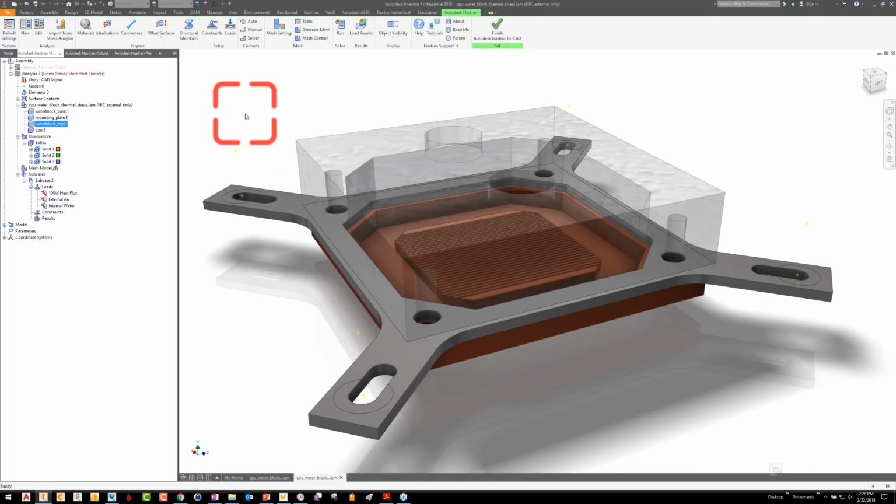Now we haven't played around with the mesh settings yet. We've really just been hitting run and letting the system run its default mesh. And the default mesh, what it's really doing, it's looking at the CAD geometry, and it's looking at the idealization for the kind of element we told it we want to use, and it's saying, okay, I need to rebuild this shape that you fed me out of those building blocks. So it's going to take a look at the geometry and rebuild it out of those little tetrahedral elements, and that's what you call the mesh.